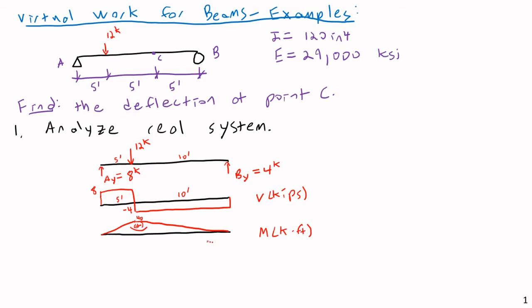And for a simply supported beam, that's exactly what we would expect, unless we had something with, say, a negative load or something. So we have that, and I can very easily then get my real moment, my real M of x. M of x, remember from the previous video, is the moment in the beam, the moment function that results from the real loading.